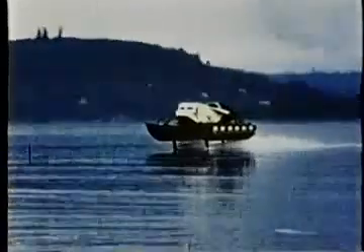We are lowering the pressure by dropping the water level above the foil by means of an upstream sluice gate. The cavity also grows when the water speed is increased. When the cavitating region extends beyond the trailing edge of the hydrofoil, we call the flow a supercavitating flow. The supercavitating, sharp-edged foil is a type used on very high-speed hydrofoil boats, such as this 80-knot boat.